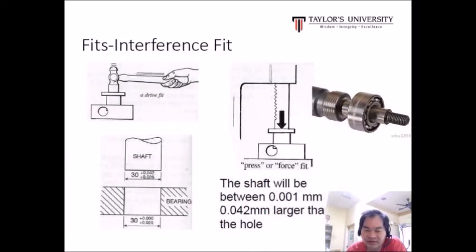How about interference fit? In this case, we need to use an external force, or the force from a press or machine, to force the shaft to fit inside the bearing.